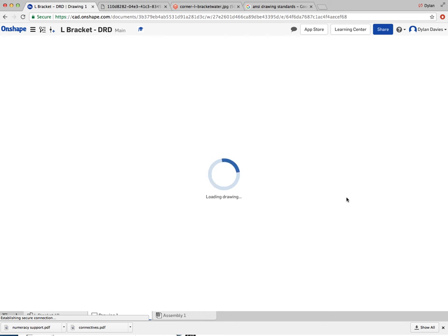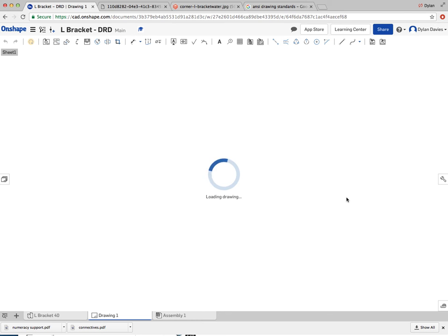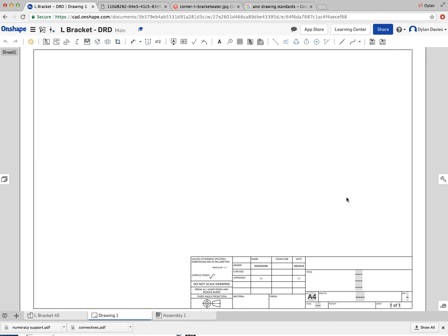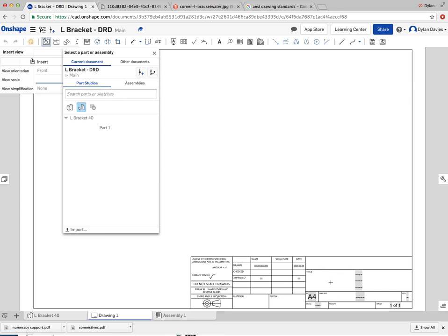And inside that template, I can add necessary detail like surface finishes. I could maybe add detail of where it's going to be manufactured or who created the design. So if I just give that a little while to load up, now this will depend on perhaps how quick your PC or Mac is able to create the drawing. Chugging away. Okay, so there's the view, and I can see the symbol for the third angle. I can add in drawing numbers, I can add in titles.